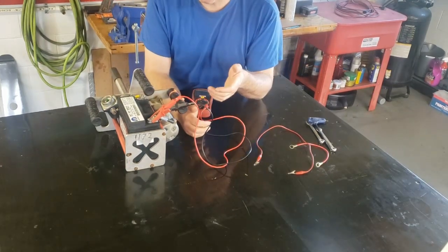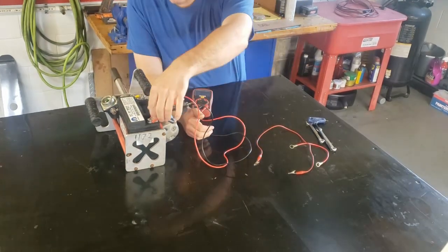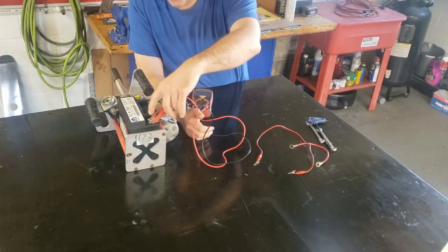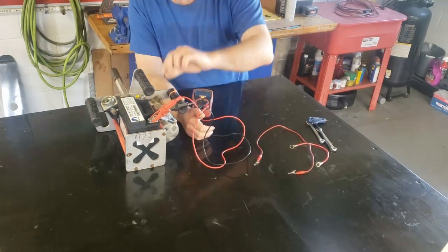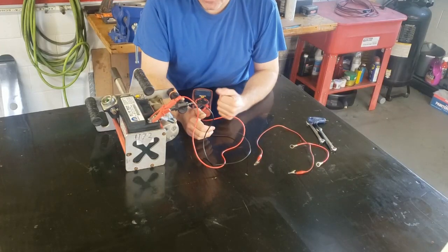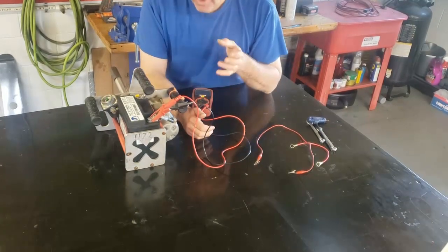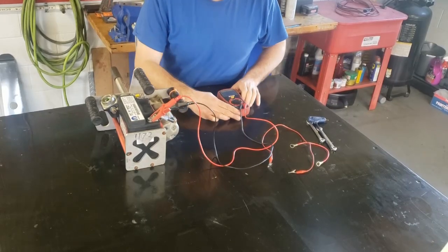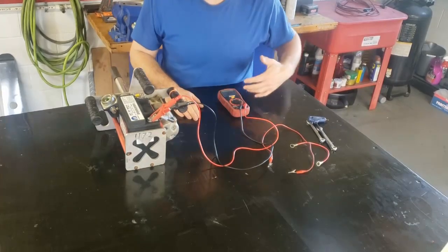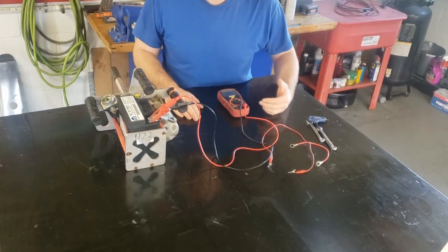It's just you won't be able to see this when we're on the actual vehicle. So again, one end of our wire, one lead is on our positive battery terminal. The other lead is on our starter motor. We're gonna go ahead and run the starter motor. Now, right now we're seeing a reading of 0 volts. We wanna see that reading maintain very close to 0 volts.